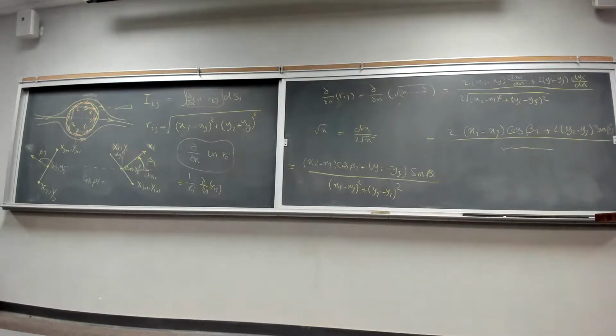And you do it for 4 panels and compare the 4-panel results, which will give you only 4 pressure coefficients because you only have 4 panels, to the 8 results you already have, and then to the analytical solution. They give you a basic understanding of why having more data points helps with the accuracy of a numerical simulation system.